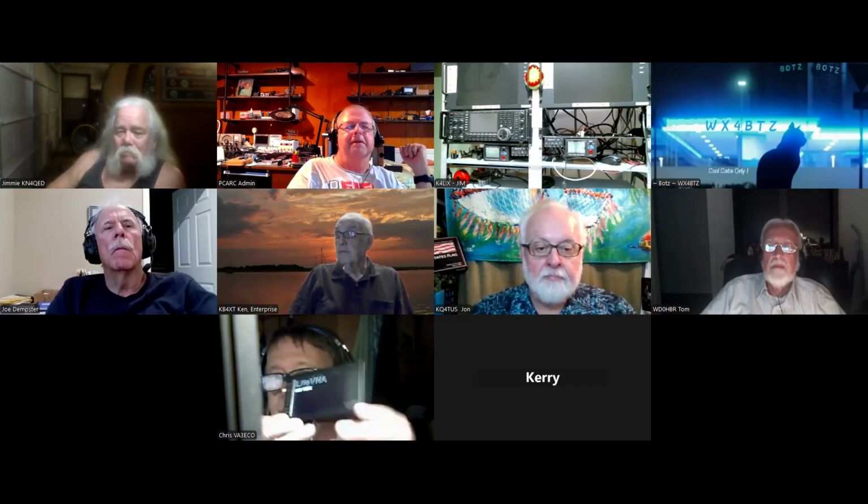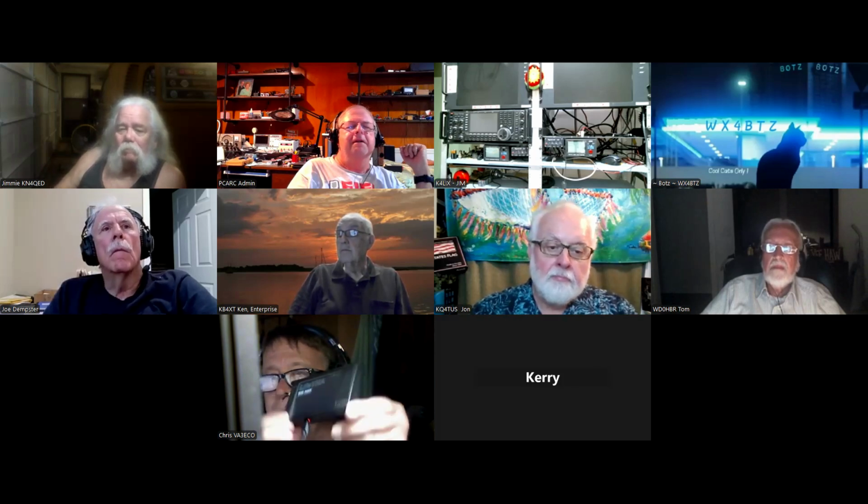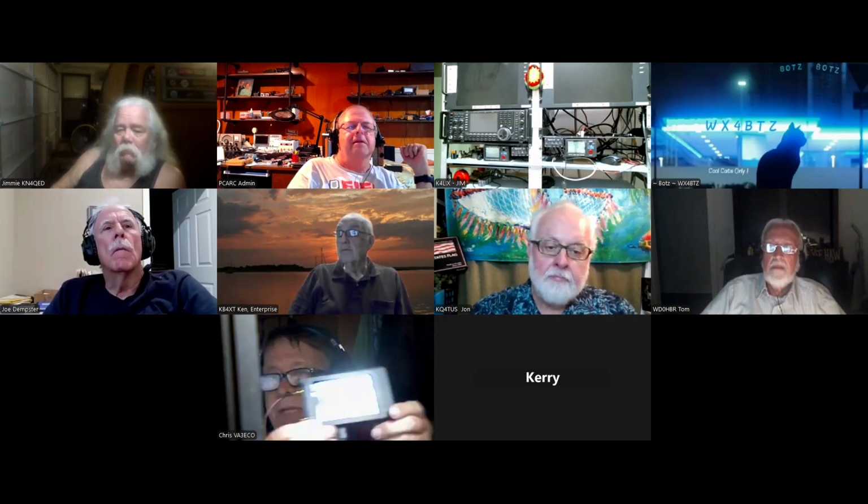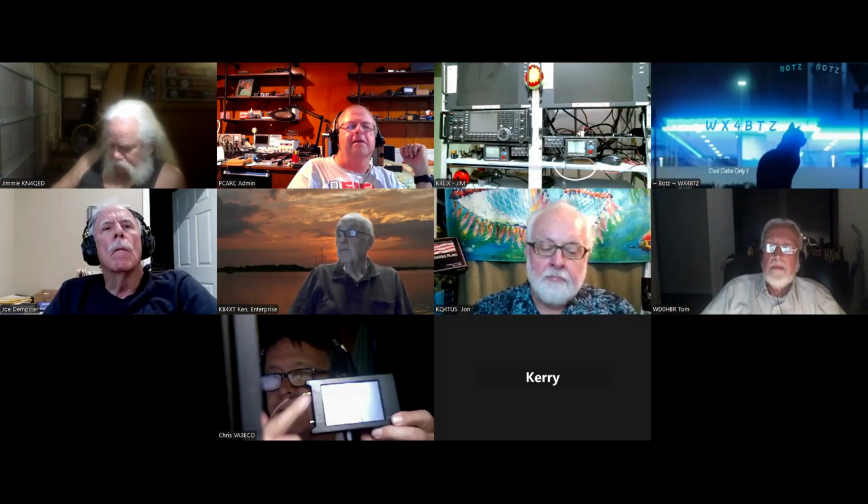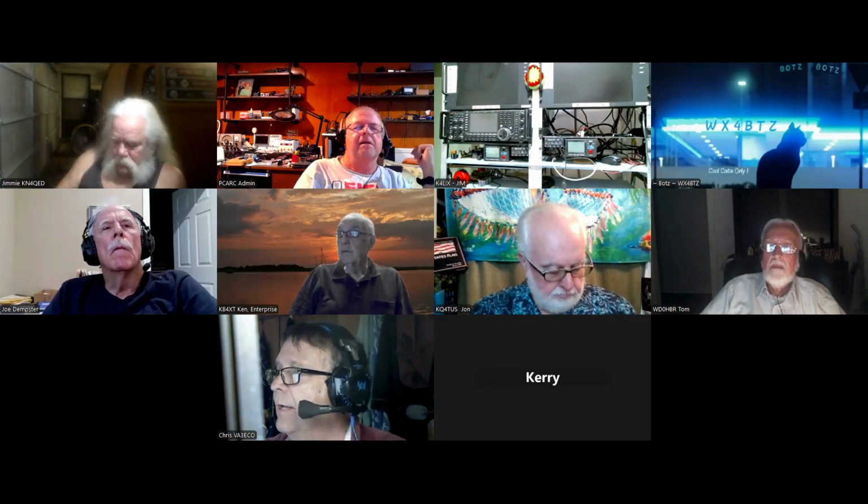And then last but not least is the VNA, which, as you well know, I'm quite a fan of. This thing is running in USB mode right now, so it's hooked up to my computer. The thing about the VNA is it's got two ports. It's got S11 and S21, and that lets you look at some stuff that a normal analyzer won't look at. In other words, you can look through things. Could I do a share, Greg? Yes.